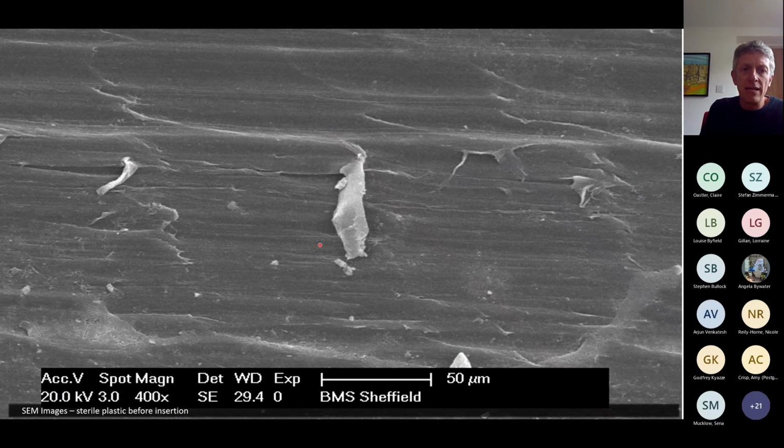So these are just some SEM images to give you some idea of what we're dealing with, what our biofilms look like. This is our clean HDPE, high density polyethylene pipe. It's an extruded material, a super smooth, shiny material, so it's lovely in terms of low head loss, so great for transporting water a long way with minimal head loss. When you look at it close enough under an electron microscope, you can see it isn't perfectly smooth. You can start to see some of the ridges and the forms from where it's extruded. You still get some scales and things, but it is still fairly smooth by most surface standards.